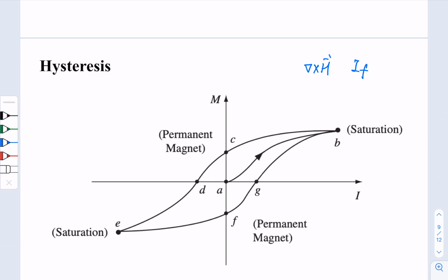In this process, now if you continue to ramp the current in the backwards direction, you will reach a point where the magnetization vector reaches exactly zero, but you need a current that's actually negative to reach that point. Now this loop can continue, and if you increase your negative current, you will magnetize your magnet in the other direction until it saturates.